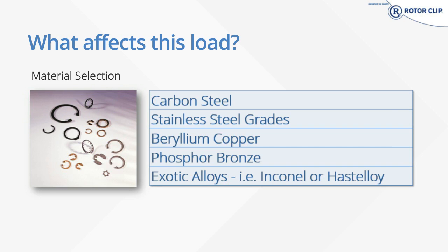Likewise, the PG value is affected by the shaft or housing material. Catalog values assume cold rolled steel with a tensile yield strength of 45,000 psi. For harder or softer materials, scale by dividing by 45,000 psi. So if you have a shaft material that's 90,000 psi, 90,000 over 45,000 equals 2, you can double the listed thrust value for the groove that we have in our catalog. And again, there are some scaling factors in the catalog for that.